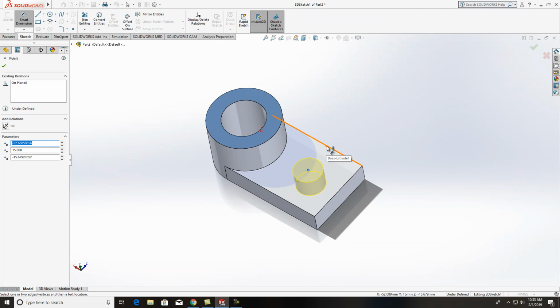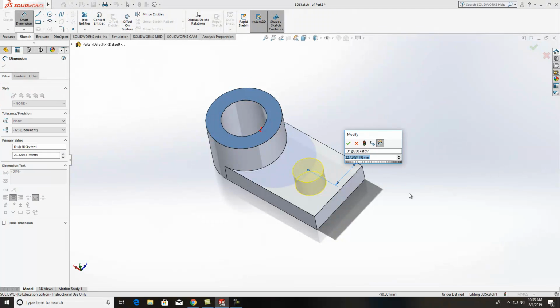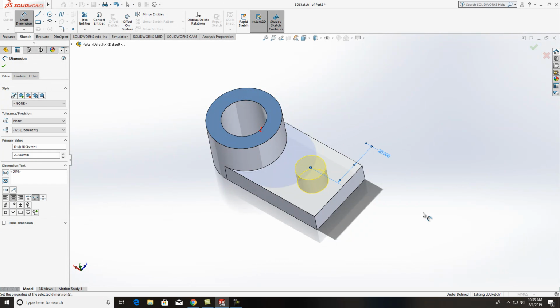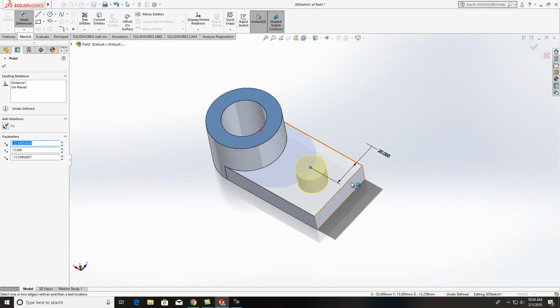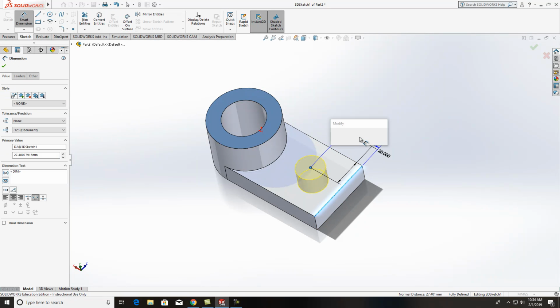I catch the center of it to the outside edge, and this thing across was 40, so you could actually type in 40 divided by 2, or it's 20, but it's really smart software. And then from the end of this is 30 to the center, so with Smart Dimension on again, catch the center of it, catch that point to that point, and it's going to be 30.